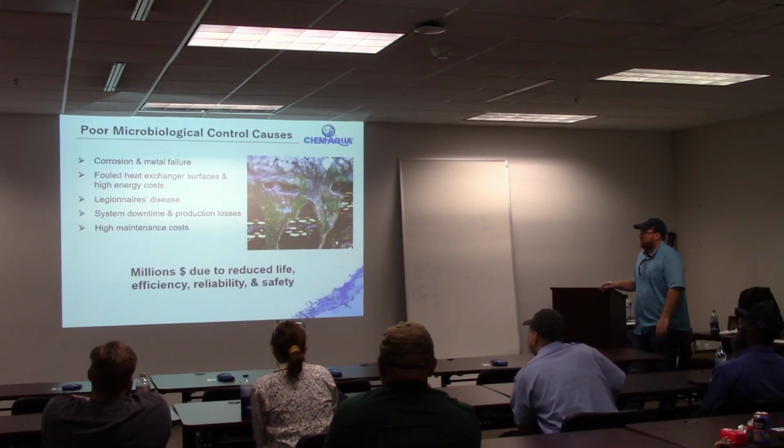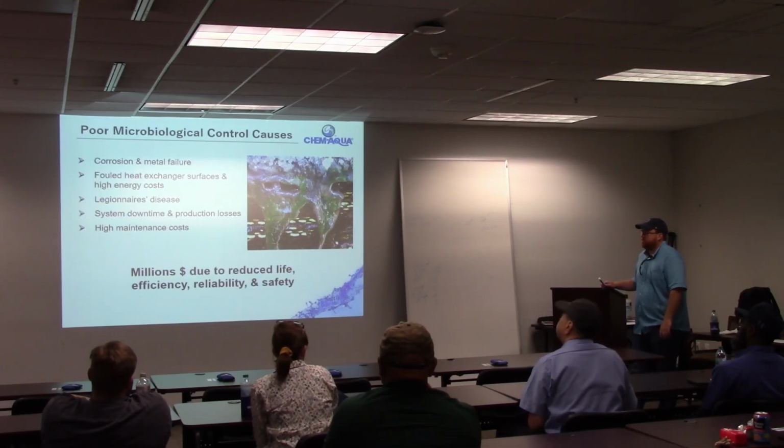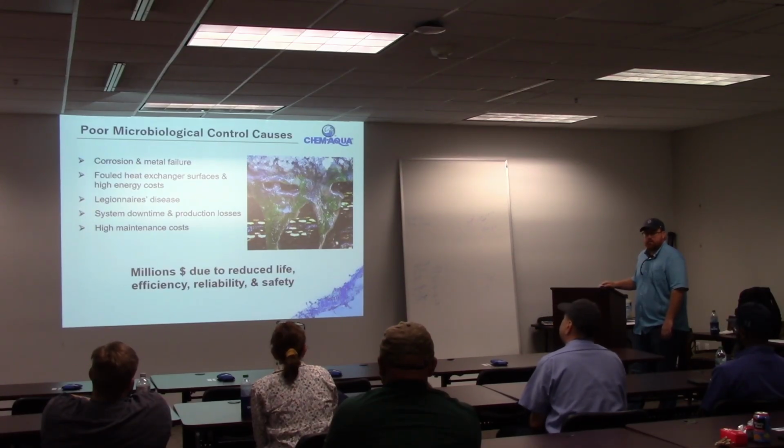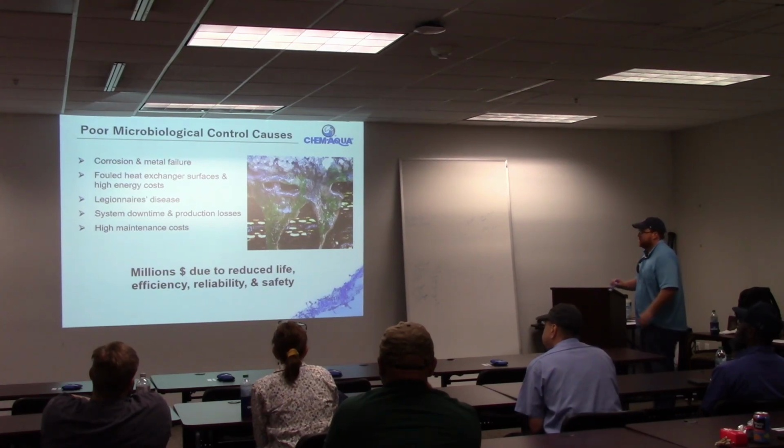We can touch on it just real quick, but it is a multifaceted approach to take care of Legionella. It's not just chemical treatment. It requires preventative maintenance, proper cleanings, proper system maintenance, all of that. So that's another reason that cooling tower cleanings once to twice per year are very, very important to do.